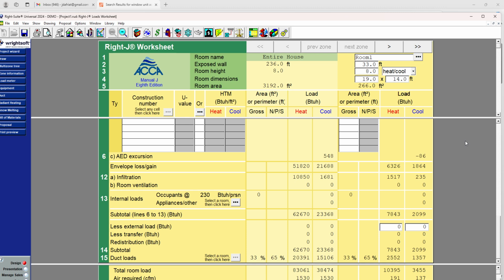Now, it also happens to be that there are building code requirements, and they are tailored to the specific region, right? So every city or county often has its own little tweaks to the building code, and they might say that, okay, in this region we require an R13 kind of cavity insulation, or if it's really cold, I suppose it's possible they could specify an R15, right? Or if you live somewhere where the weather's really nice, maybe they'd only specify an R11. Okay, but the building code generally does specify some of the basic minimums, and of course, a homeowner may choose to do better than that.